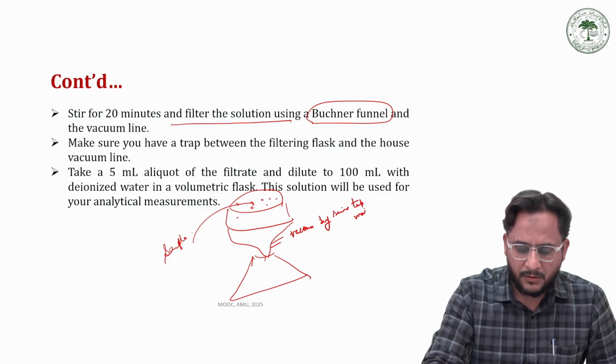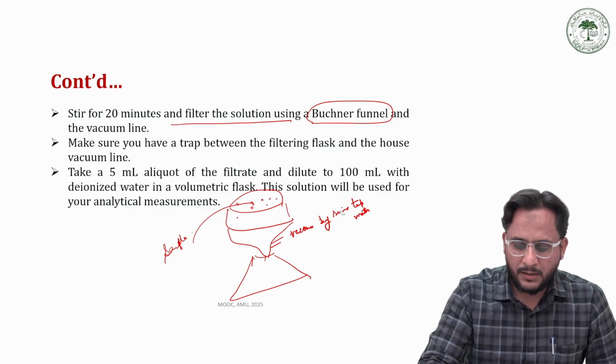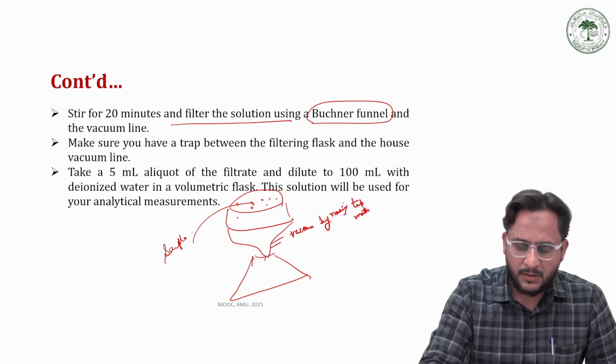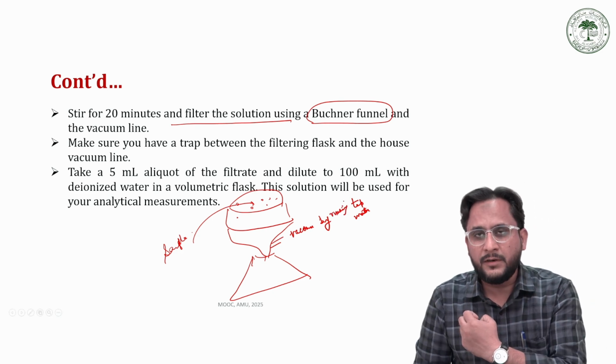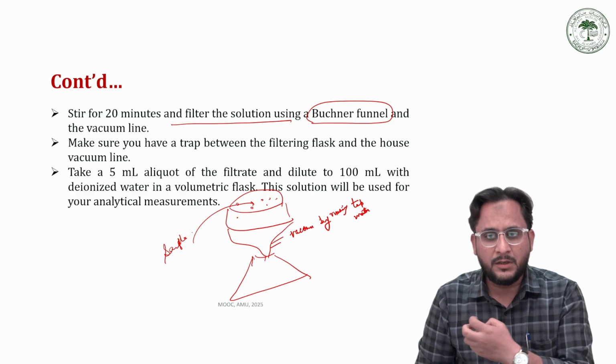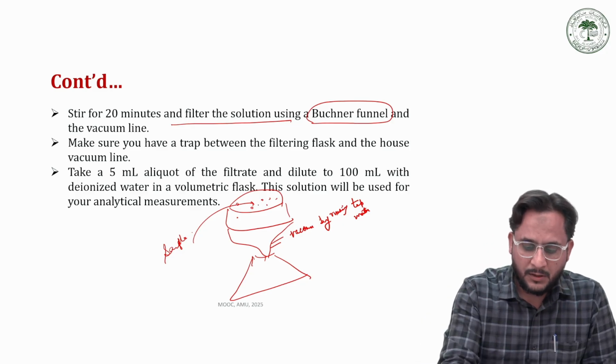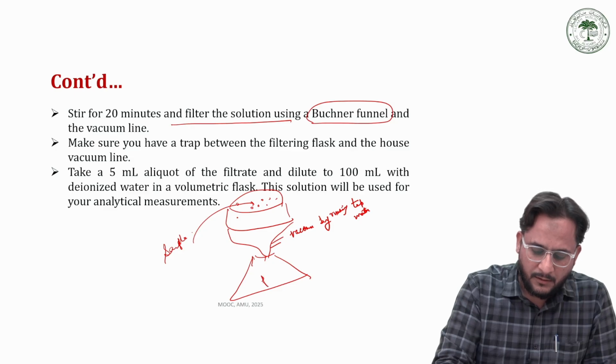We pass tap water which removes all the air, and a vacuum is created, and that vacuum pulls the liquid through these pores, resulting in a fast filtration process.